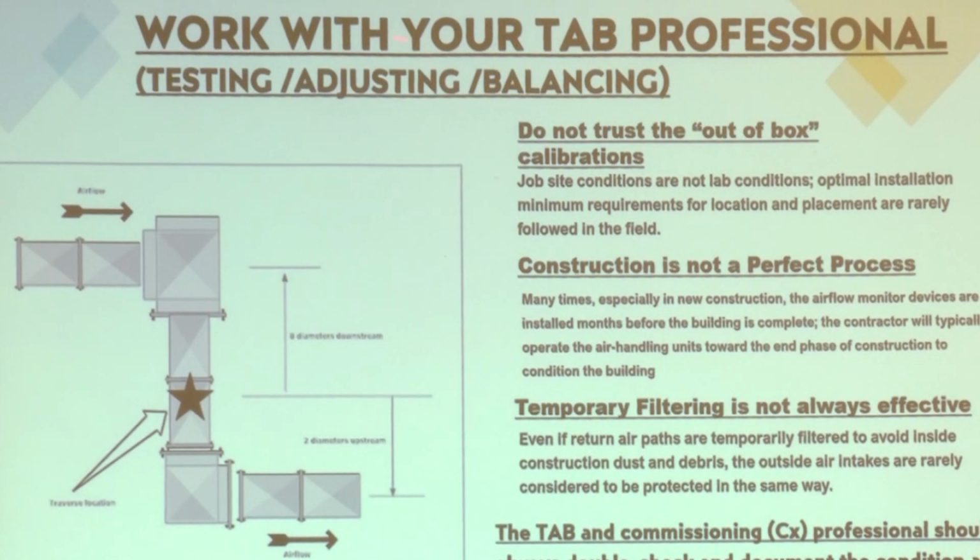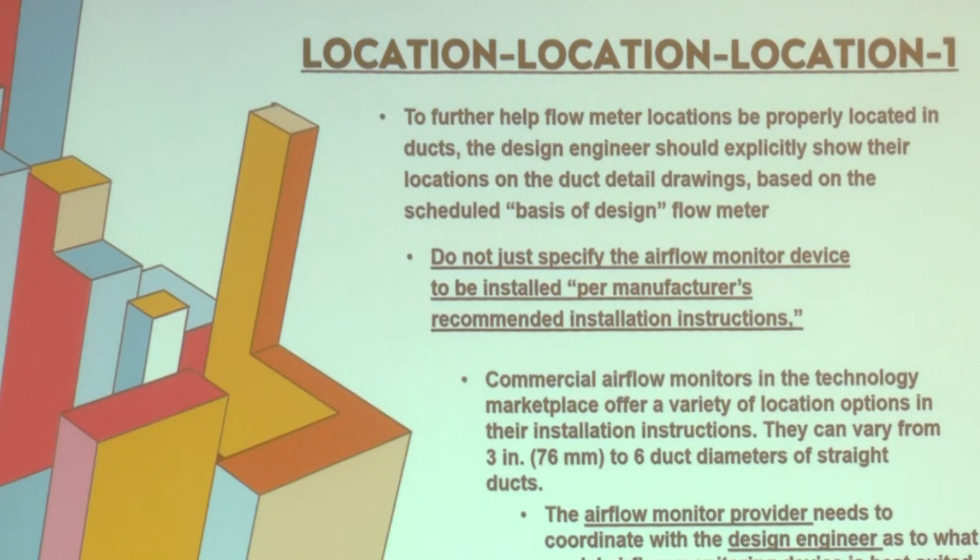So what I'm saying is, work with your TAB professional and make sure that those calibrations are done during the TAB process. Do not trust those out-of-box calibrations because they're not correct. Those are all done in a laboratory, so they don't apply to real-life systems. And that TAB and commissioning professional will help you get there.